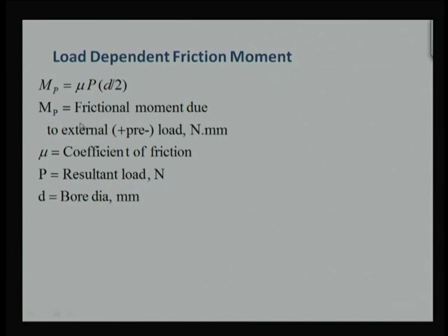And when we are talking about the force P, we are assuming there is an external load. In addition, there is a possibility of preload. What is the meaning of preload? We say in a bearing, if there is no clearance or there is a negative clearance, then there will be some load initiated or developed within a bearing that will be different than the external load. How will this kind of load be generated?